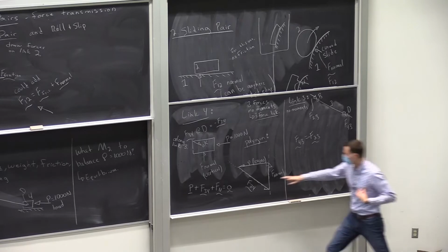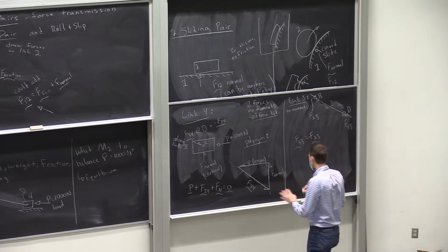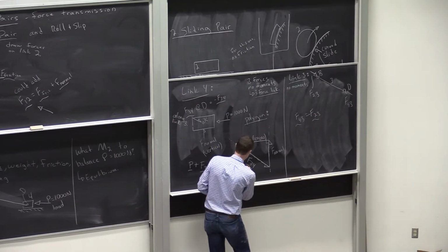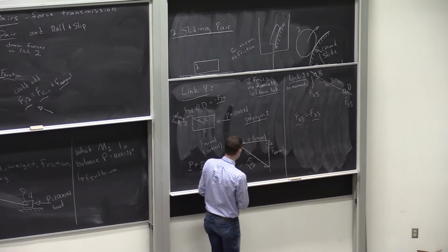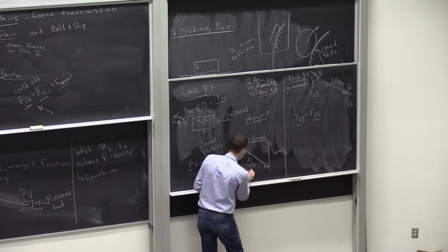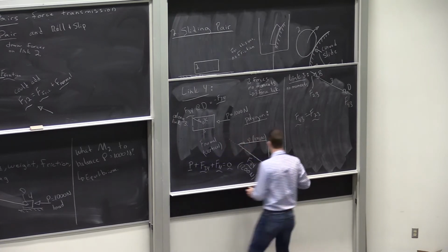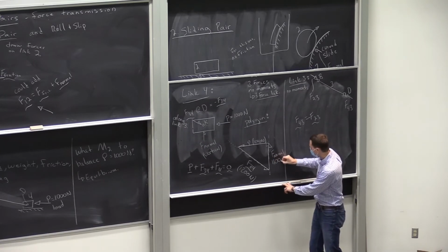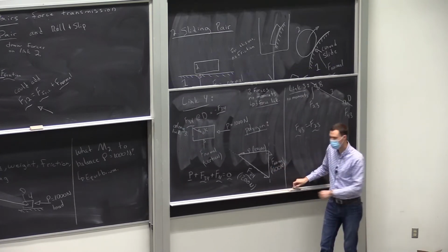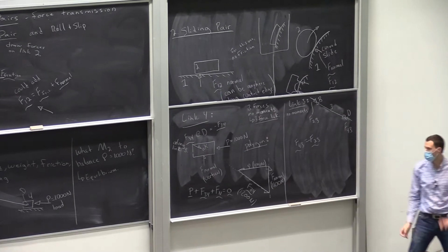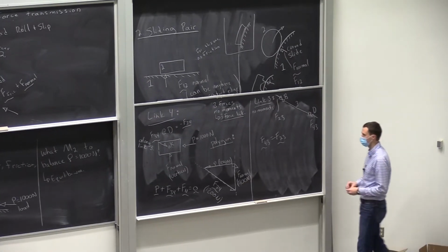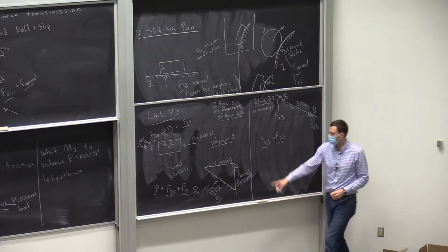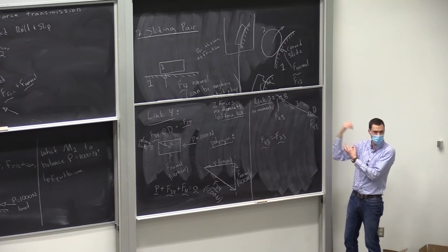That's our force polygon. We can measure on it. I'll just eyeball this one here. Let's say F3/4 is, what do I have, like 1,200 newtons, and the normal force is 1,100 newtons. Okay, you measure it on your ruler by doing a detailed diagram for accuracy. Good. F3/4, 1,200 newtons. Now it propagates. Now we've propagated information forward.